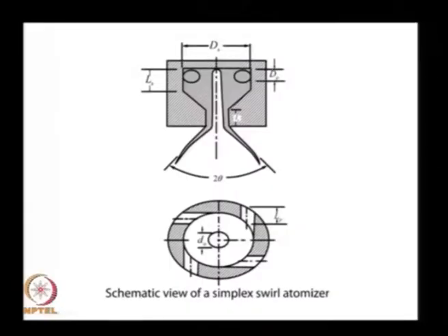Simplex swirl atomizer is by far the most commonly used of any spray nozzle design. The basic principle of operation is this. So, imagine this is my nozzle. Instead of injecting the liquid straight through from the top and allowing it to accelerate through a converging passage, what is done is the fluid is injected through a set of tangential slots.